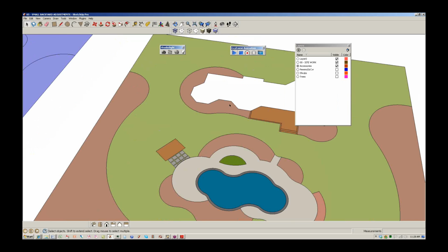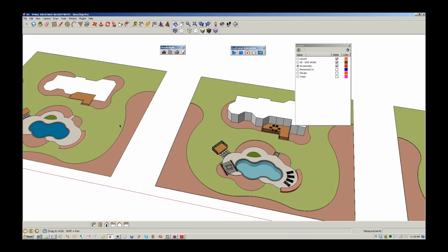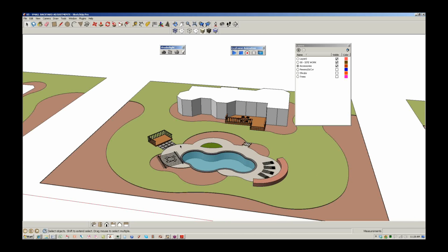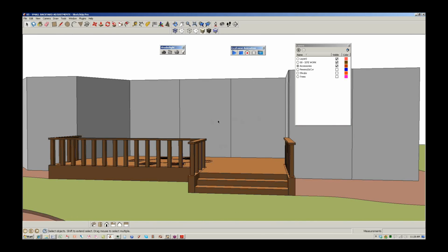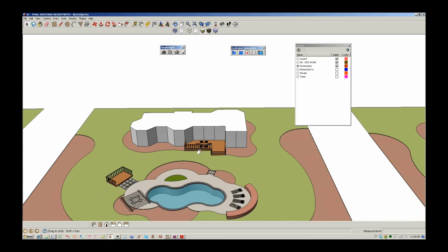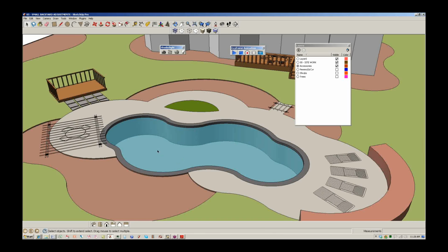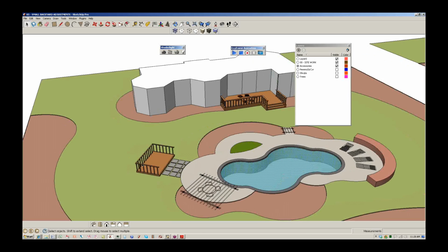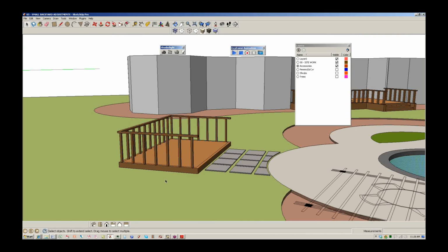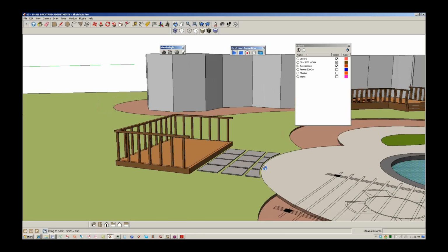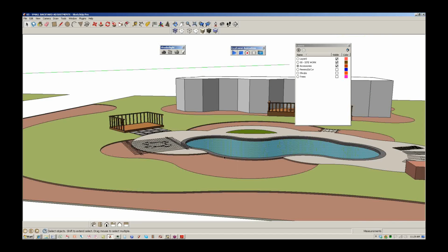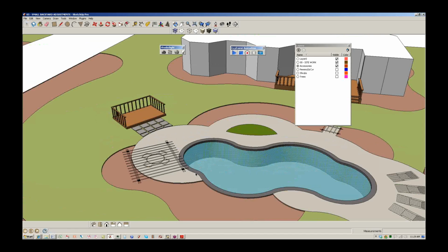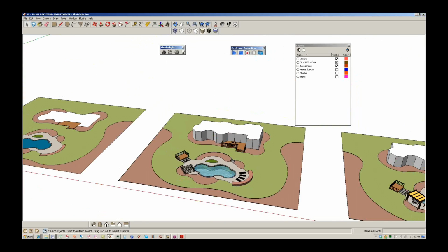a little bit of another planting bed, and then I start extruding everything. So I've extruded the steps on the deck. I've extruded the building, so I'm just modeling in SketchUp. This didn't take me very long to do. I created a pool and a pool surface, so there is a pool surface underneath here, and then the pool surface itself. I added some detail in for some of these little areas that are being articulated, these architectonic elements within the site plan, and I've actually pushed, pulled down, or extruded the planting beds themselves. So that's the next stage of what you're doing.